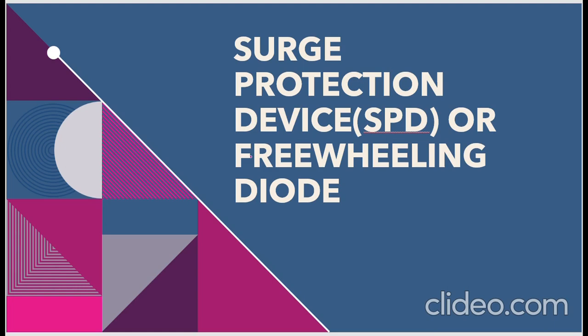Whenever these contactors or coils are actuating, some voltage or current may dissipate, which will cause damage to another component or some electronics failure. Because of that, we use a surge protection device or freewheeling diode.